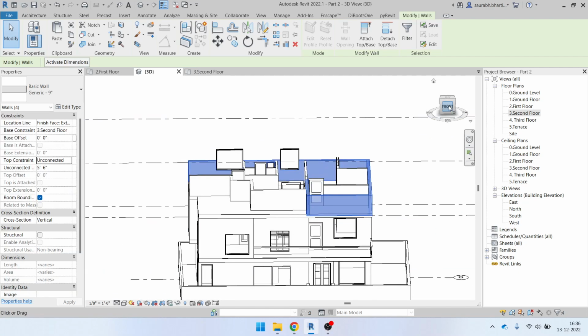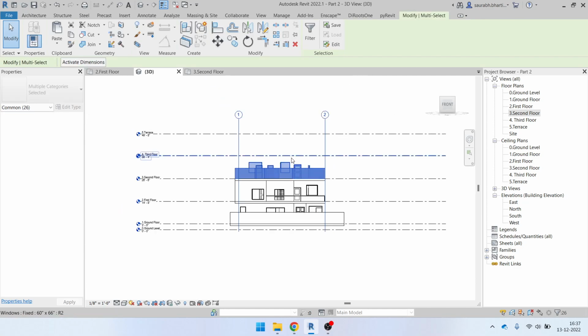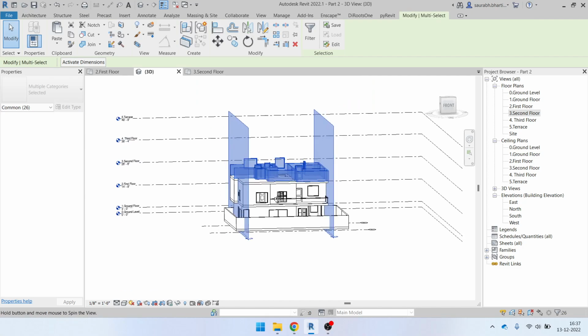So what we are gonna do is, here I would have already told you about the selection. If you go from right to left, whatever you touch fully will get selected. So if we are touching something halfway, it will never get selected. But if you go from left to right, whatever it touches will get selected. So I have gone from left to right.